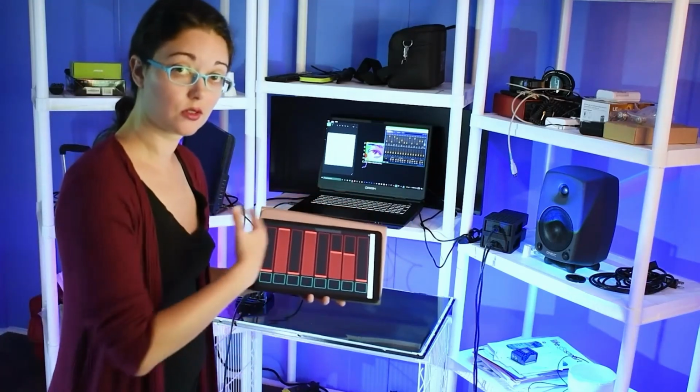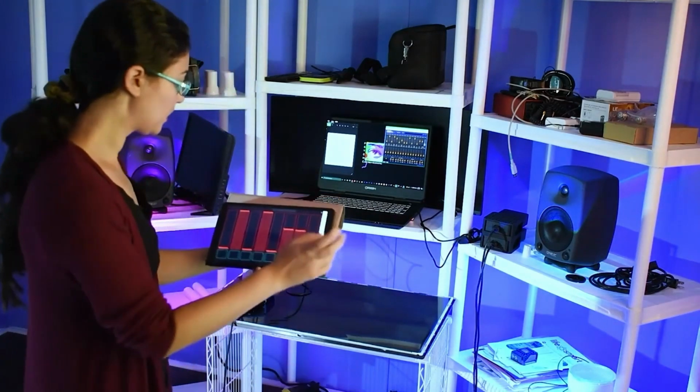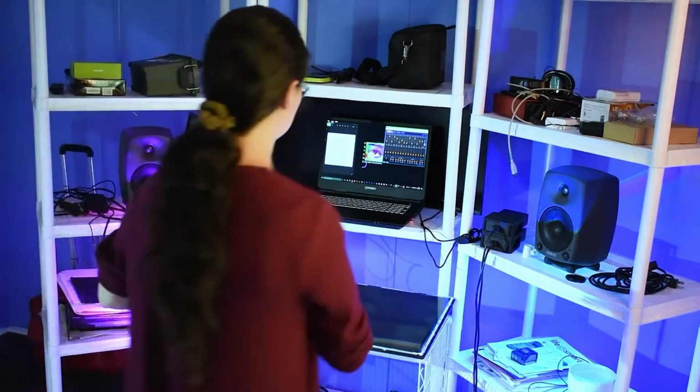Again, these channel configurations are not going to be the same for every light. You really do need to study the spec sheet of the particular fixtures you're working with to know how to access the functions of the light and then how to control the functions of those lights. Let's access another function. Let's go back to light number 1, channels 1 through 8.